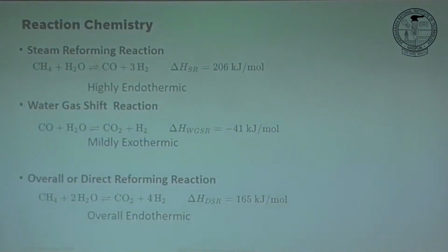So in process design, if you remember from your courses, does everybody know about the onion model? In process design, you normally start with the reactive system, and you go with the separation next level, and then you think about heat integration, and finally whatever heat balance is there, you either cool the remaining heat via utility cooling or so, right? So we'll start with the first step, reactive system, reaction chemistry.